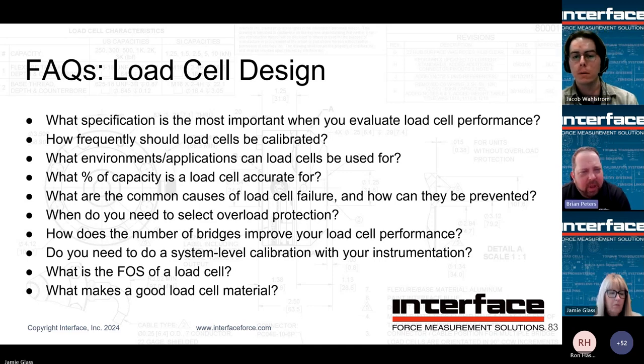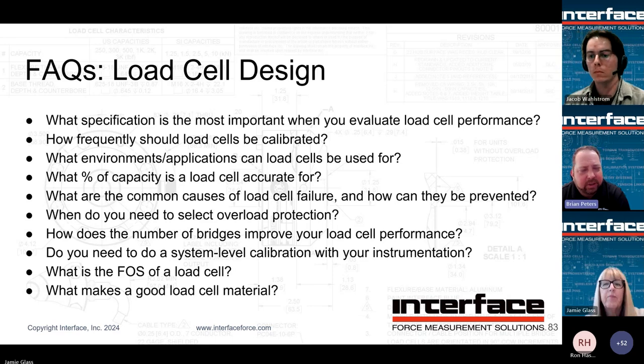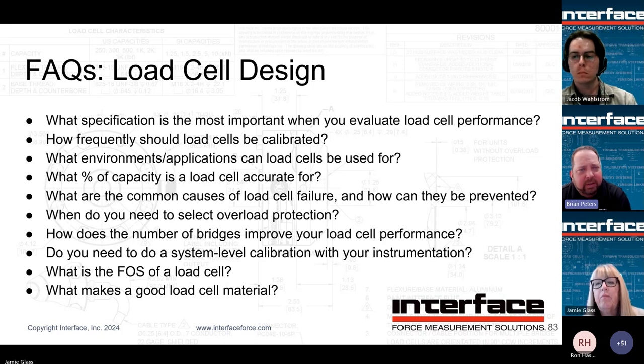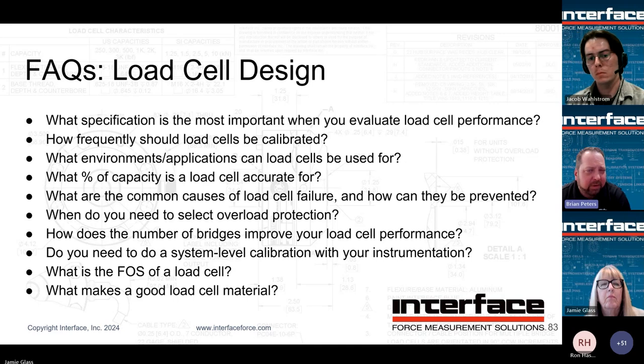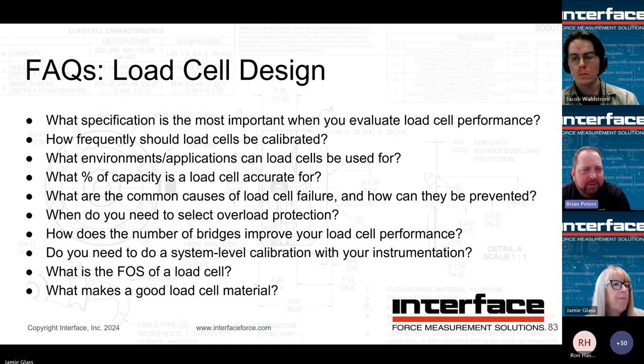Good. All right. Do you need to do a system level calibration with your instrumentation? We didn't get into too much detail when you start talking about different calibration options from a component to a system level standpoint. You've got the calibration of the load cell. You've got the calibration of your instrument. How accurately is it reading millivolt per volt, for example? If you're using TEDs, of course, it really becomes important as you swap out sensors. But typically,